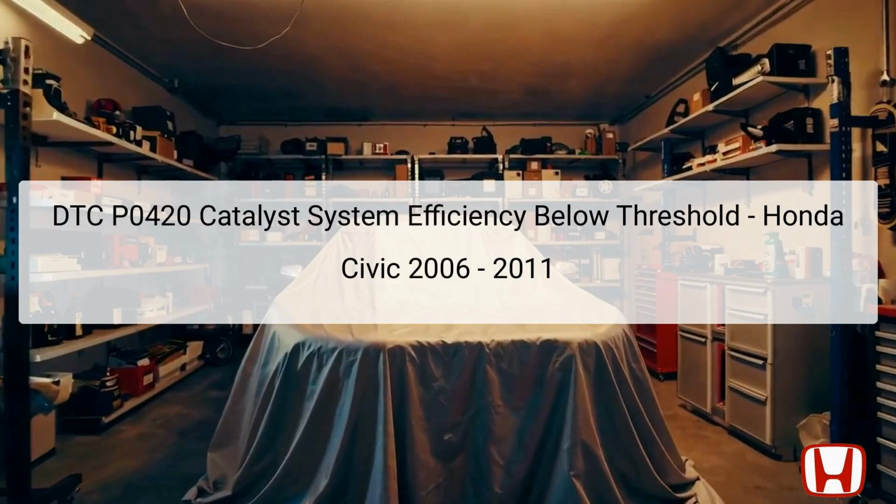When the emissions output exceeds the expected threshold, the Engine Control Module, ECM, triggers the DTC P0420. It's important first to record freeze frame data and any onboard snapshots before initiating troubleshooting. Notably, this DTC may appear alongside other codes such as P0137, P0138, or P0141, which pertain to the secondary O2 sensor and its heating mechanism. Addressing these associated codes is essential prior to resolving the main DTC P0420, as they can provide further insight into the issue at hand.